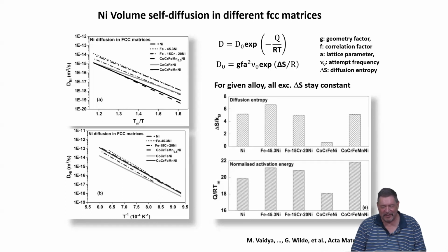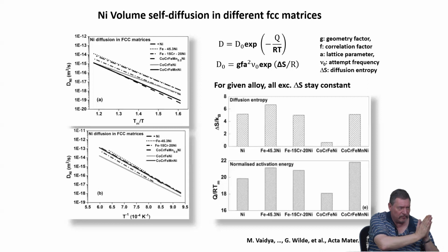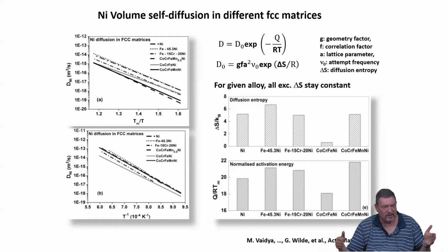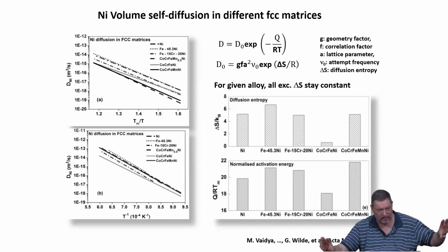Yes, yeah. But I will show you more on this in the next 4 lectures next week, especially on how you can also test this hypothesis in a different way, not by changing the alloy from a medium to a high entropy alloy by adding a new constituent, but in a more clever way, I think: always keeping the 5 constituents the same, but within these 5 constituents changing from a dilute alloy up to the high entropy system, and monitoring how the system properties change, going from an almost pure single phase material with some minor additions up to the high entropy system.